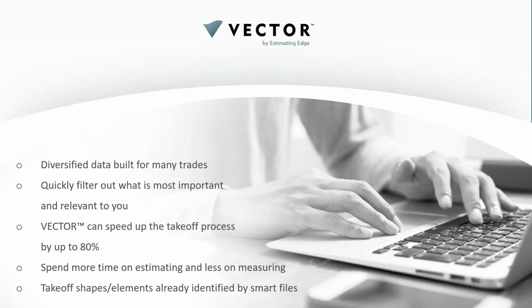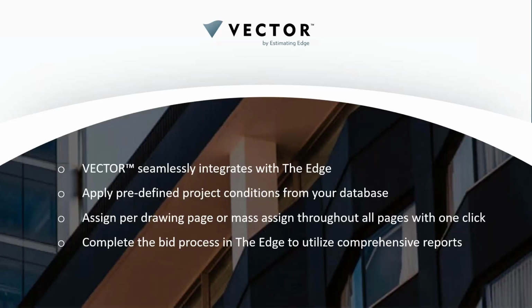All right, and we can do this because we have the shapes and the elements from the model that contain the quantities that the architect gives us. Okay, so again, this is just a reminder, it integrates with the Edge. We're going to be pushing data from the model to the EDGE Estimator, and you'll still have your conditions, you'll still have your items, all your formulas. And what I want you to watch out for once we get into the Edge is how we take the shapes from the model, we visualize their quantities, and we map them to the conditions that you use every day.